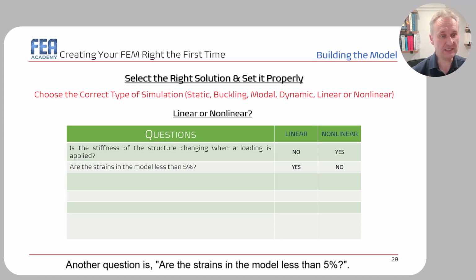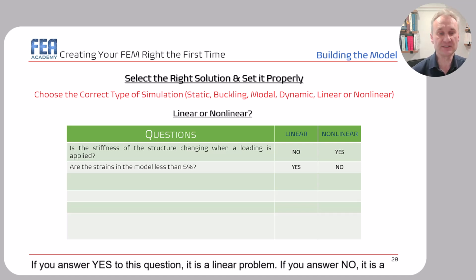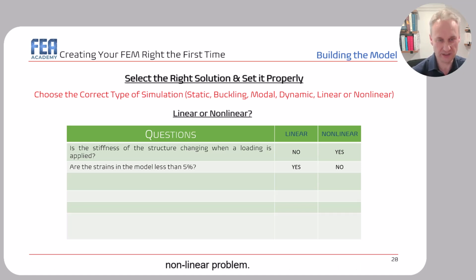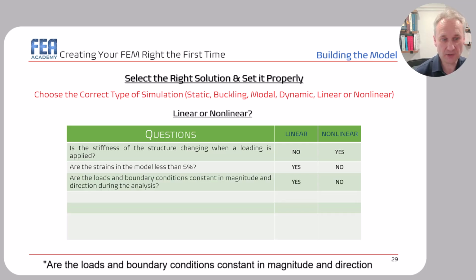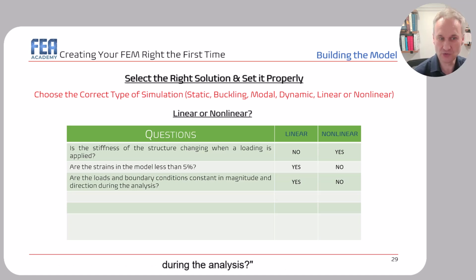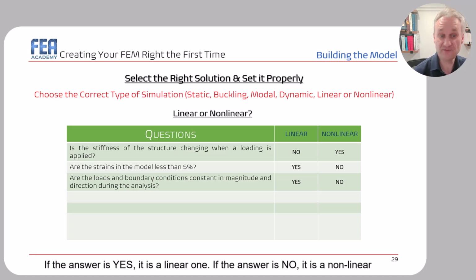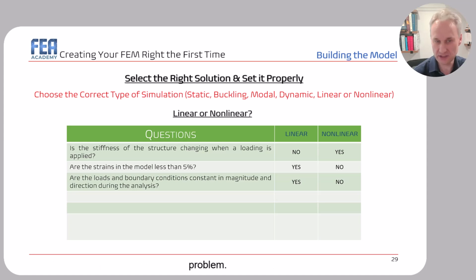Another question is, are the strains in the model less than 5%? If you answer yes to this question, it is a linear problem. If you answer no, it is a nonlinear problem. Are the loads and boundary conditions constant in magnitude and direction during the analysis? If the answer is yes, it is a linear one. If the answer is no, it is a nonlinear problem.